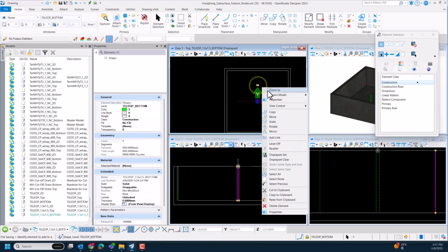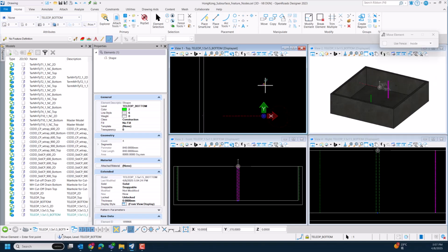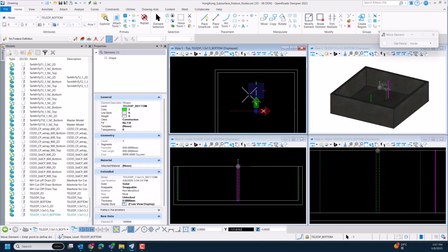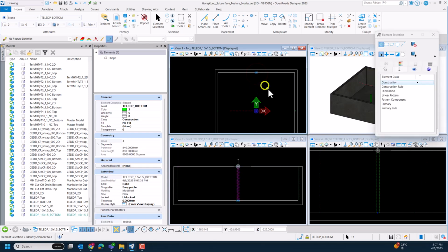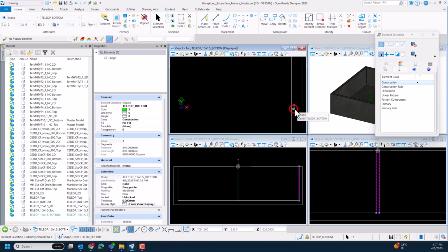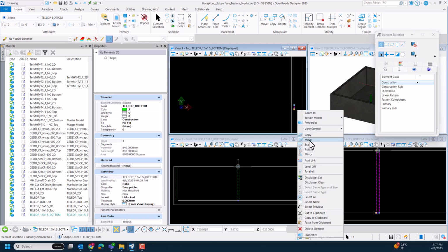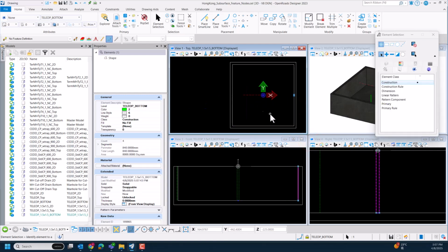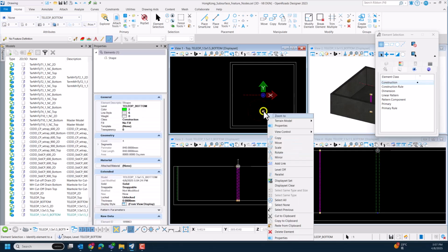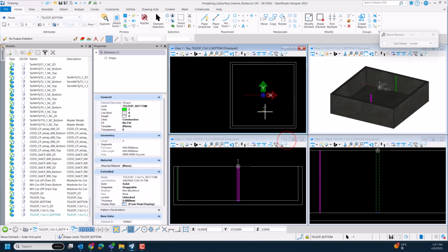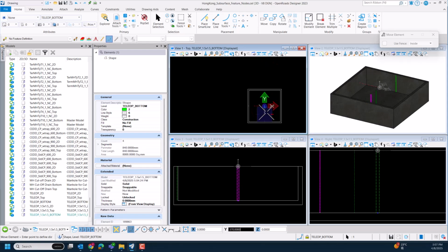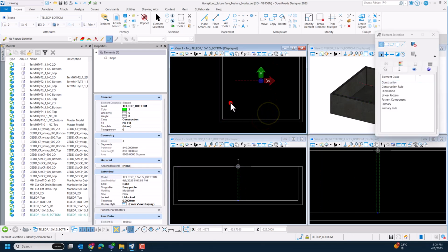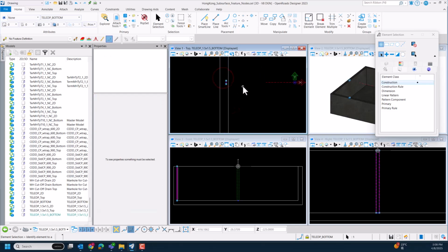Okay, so I right click on one of them and then modify the position and keep the offset at 0 and snap on the face of the node. And again, I can move this one to this position and do the same to other connection surfaces. And there's another one.